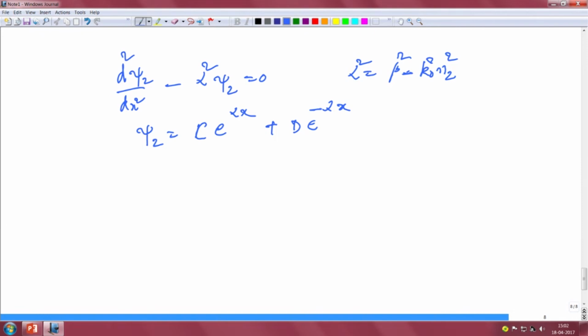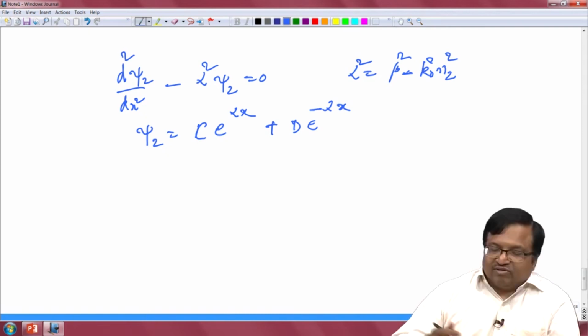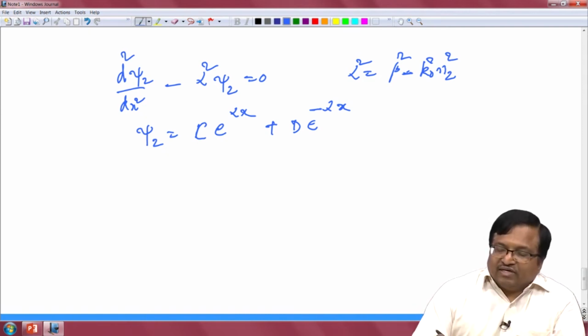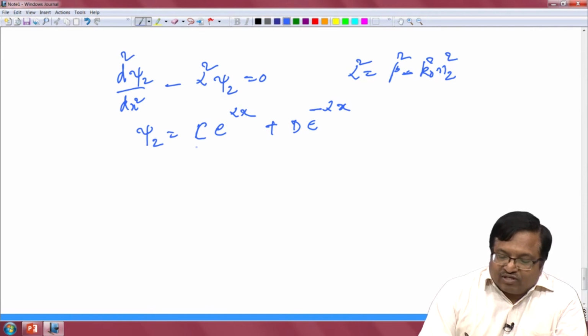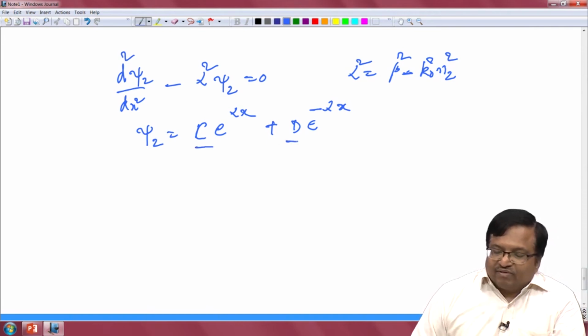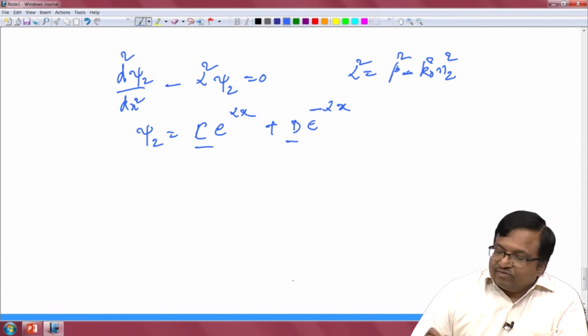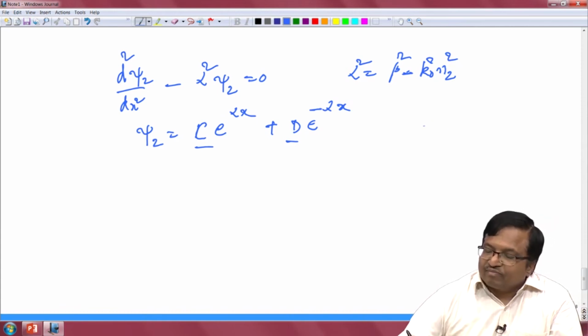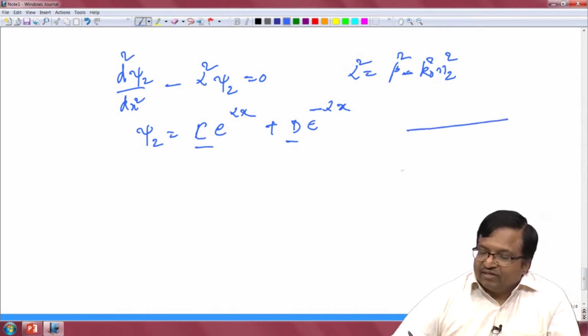We can take a physical explanation saying that the desirable form of the fields of an optical waveguide is oscillating fields which gradually decay to infinity, and choosing the constants will be an important problem now. So, if you look at the waveguide and the equations, we can say that the field should be continuous at the boundary.